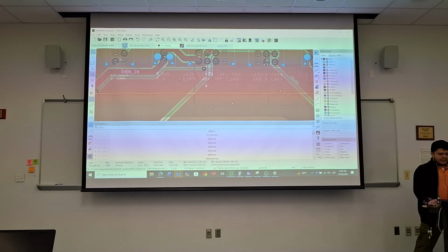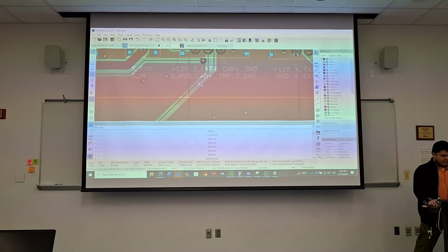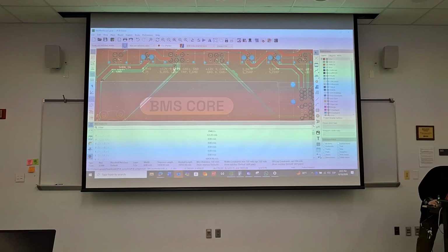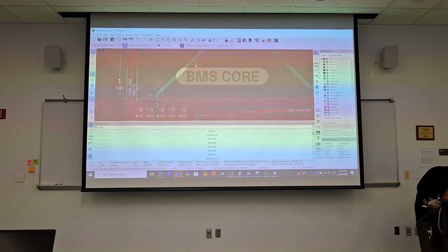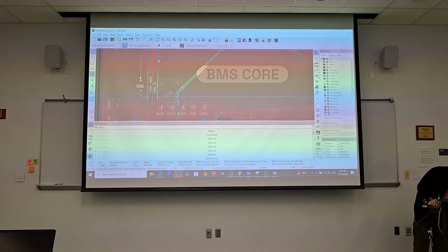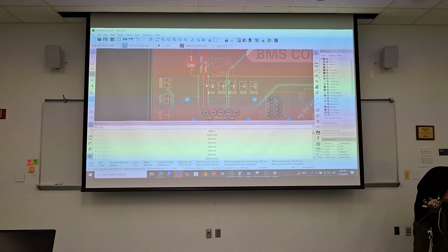What helps here is checking this controlled impedance, because I'm pretty sure this isn't helping. I see it's a solid reference plane, but this could use a lot more grounding vias or shielding vias. I see some sense lines on the bottom layer that are not properly referenced.